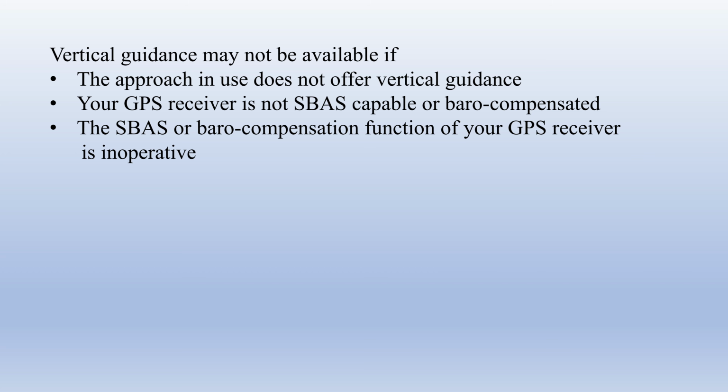And then on some of the receivers, even in Microsoft Flight Simulator, you have the option of turning these functions off. For instance, on the GNS 530 and 430, you can actually go into one of the menu options and turn the WAAS system or the EGNOS system off, so it becomes an old-fashioned LNAV receiver without vertical guidance. So if you want to try flying those types of approaches with that receiver, you can do that.